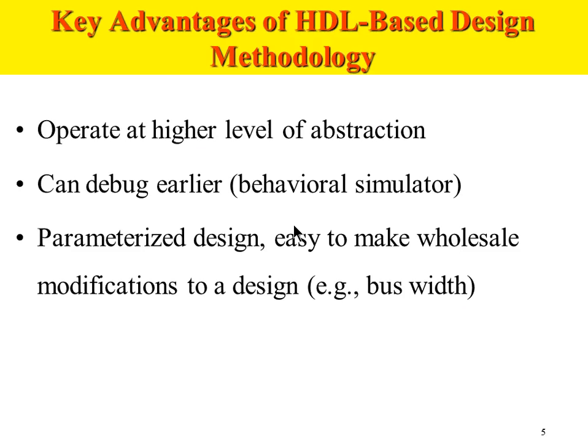So the other advantages of HDL based design methodology is we operate at a higher level of abstraction. When we do schematic designs, we work on gates at a gate level abstraction. So gates and components from the library. So we take the gates and the various components and then we interconnect them and create a schematic or a netlist out of it.